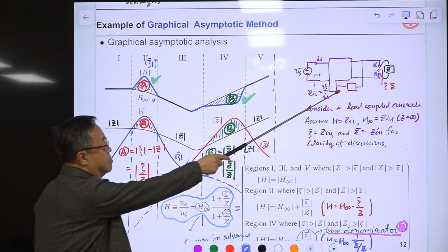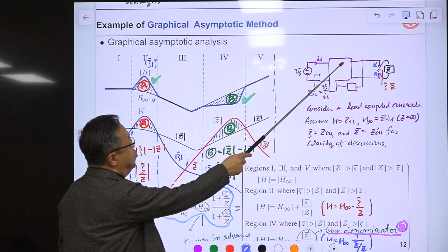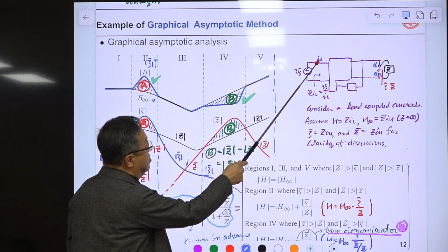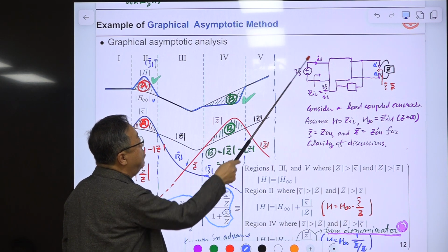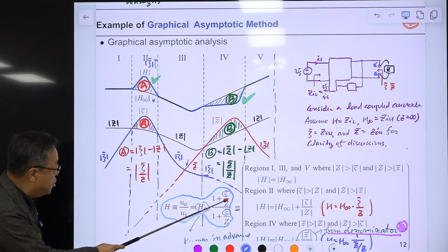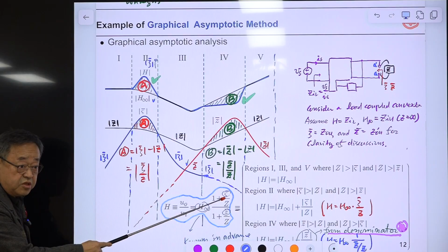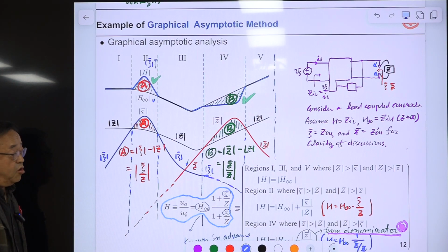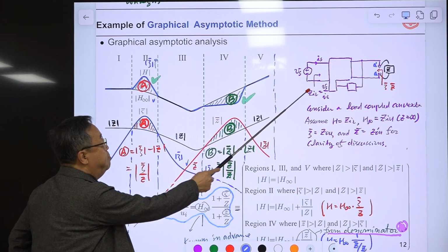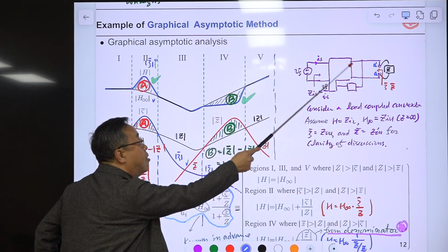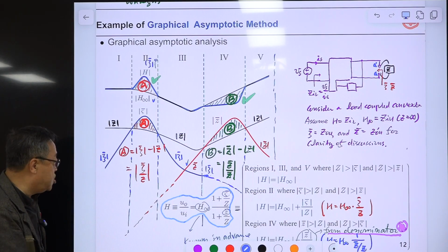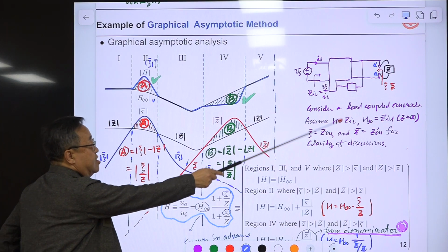This is the load-coupled converter, and you are interested in its input impedance, which is the transfer gain from this input current to this input voltage. So this is the general equation for that case. This is the EET formula. For this special case, H is GIL, the input impedance of this load-coupled converter, with this G present. And H infinity here is, this guy is gone.